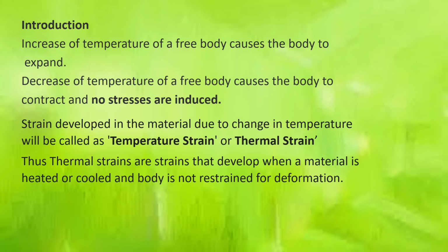Increase of temperature of a free body causes the body to expand. Similarly, the decrease of temperature of a free body causes the body to contract and no stresses are induced. The strain developed in a material due to change in temperature will be called temperature strain or thermal strain.